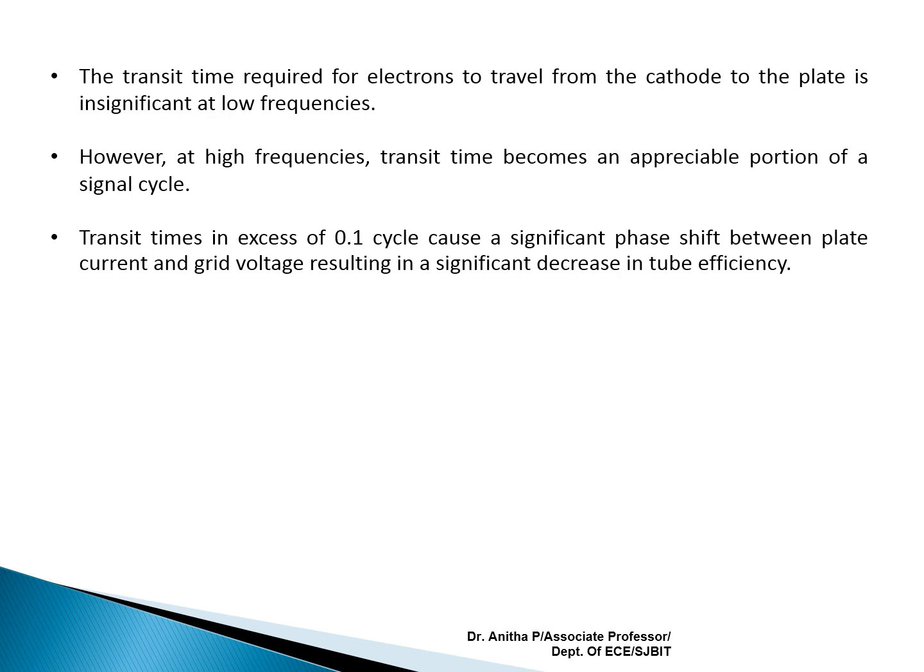Similarly, there are radiation losses. If I give an input signal, then instead of amplifying the signal, some of it gets radiated into free space. If I operate at very high frequencies, instead of amplifying the signal, some of the signal will get radiated. That radiation has to be eliminated. All these effects limit the use of conventional tubes in the gigahertz range, that is, in the microwave range.